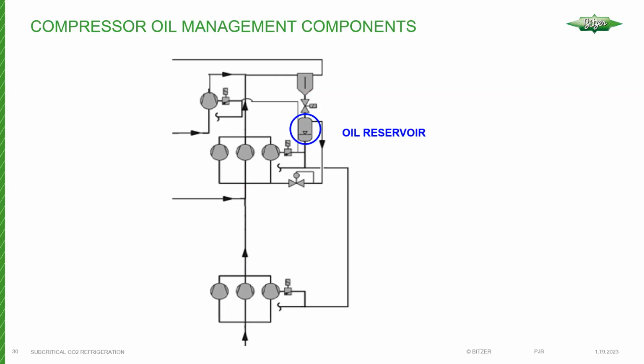As the oil level accumulates in the oil separator, at some point the optical switch is going to sense that there's oil there. When it does, that's going to initiate a dump cycle, or transferring oil into the oil reservoir. So the optical switch on the side, which we don't see here, would say, hey, I've got oil, and it would tell the solenoid to open.